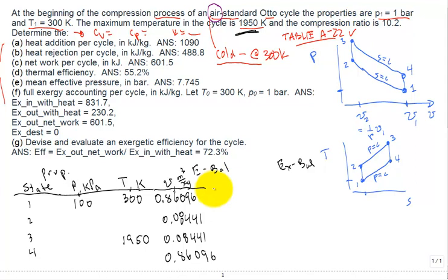And so how would I solve for this compression process from 1 to 2? Well, we know that it's isentropic, S equal to a constant. And there's a particular column in the air table for what we call V sub R. I don't have enough room to put all these tables on one slide. And we can look up the V sub R as only a function of temperature.